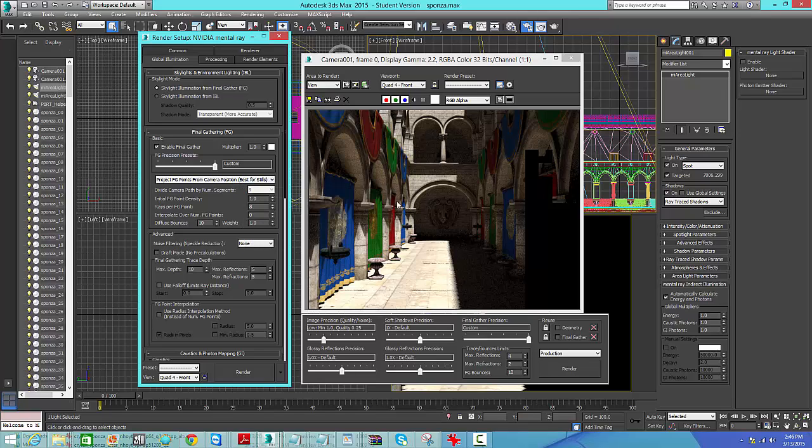Then it's shooting the grid out from the same spot every time, wherever the camera is. With this one, it will use the path of the camera to generate the grid. So wherever the spline of the camera is going, it will generate the grid in a method that follows the actual motion. So this is helpful if you have a large camera move or something like that.